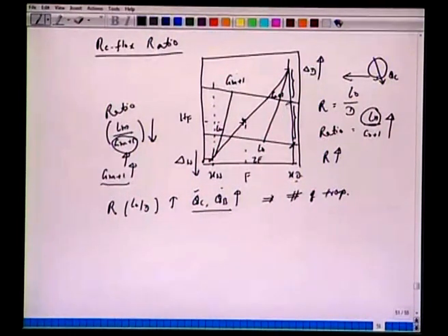All right. So, the number of trays: if you recall, we had stages like this, connected with the second stage, all the tie lines, the equilibrium lines which we have drawn from the operating curves, wherever it intersects. Now, if this point moves up and this point goes down, you can see the trend of the tie lines you have drawn: they become vertical and vertical. You should plot it and convince yourself that the number of trays will decrease.